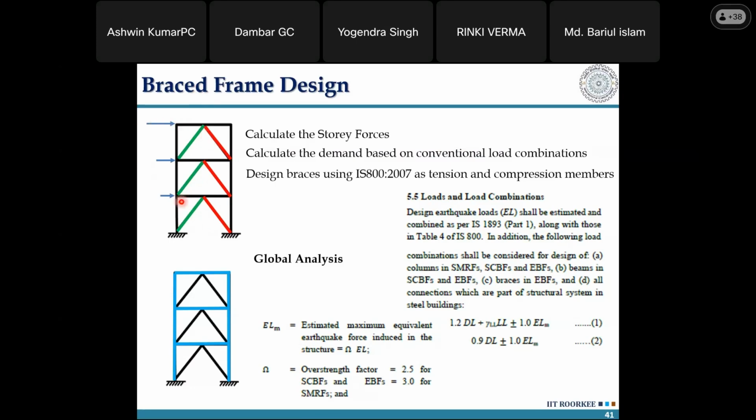Do braces give nonlinear hysteretic damping? Yes. When some brace member goes into nonlinearity, with tension compression forces, it is yielding, then obviously it is going to increase the damping in your system. Normally we design the system for 5% inherent damping, but when a brace member undergoes inelastic yielding and compression buckling, the damping ratio might increase to 20 to 30%, right? So that decreases the vibration in the system. Now, without any disturbance, let me finish this particular part, which is important.